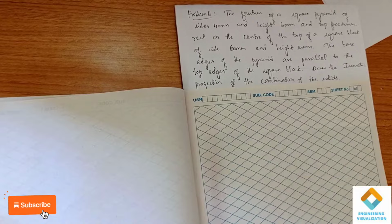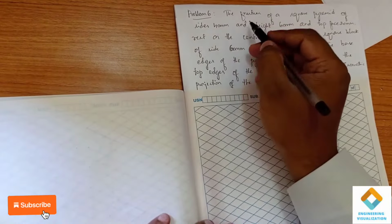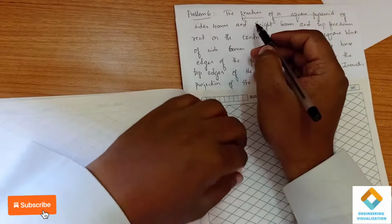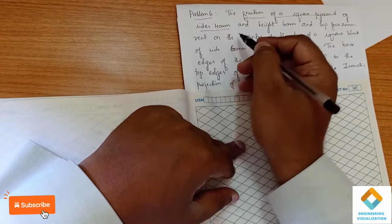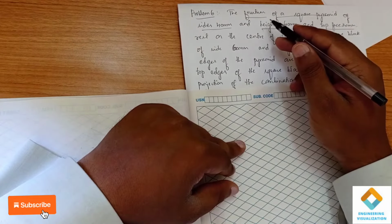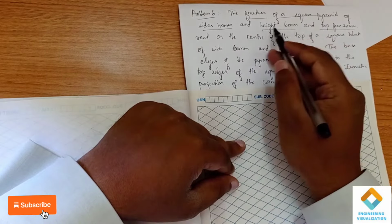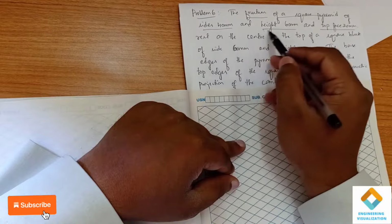We see another problem in isometric. So here in this problem they have given the frustum of a square pyramid. Frustum means it is a cutted portion of a square pyramid of base side 40 mm and height 60 mm and top is 20 mm. Okay, so frustum means it is a cutted portion of the square pyramid, wherein the top face and the bottom face will be squares. The top face is 20, bottom face is 40 and height given 60.